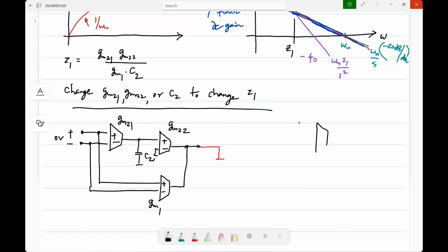what is a reasonable model for the noise of a transconductor? Again, I think we have discussed this before. So what's the noise model? What model should I use? I think you must have used this in the assignments also, right? So basically it will be 4kT gm. If nothing else is given, you can make transconductors with noise much more than this, but you probably cannot make it much less than this. But there may be some small factor, like if you use MOS transistors, you will get another factor of 2/3. Instead of 4, you get 8/3 and so on. But otherwise, this is a standard model for noise, just like for resistors.